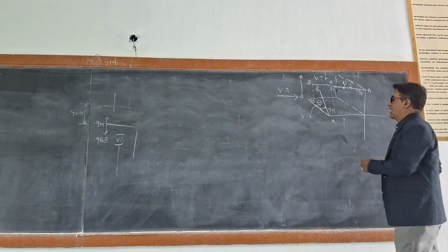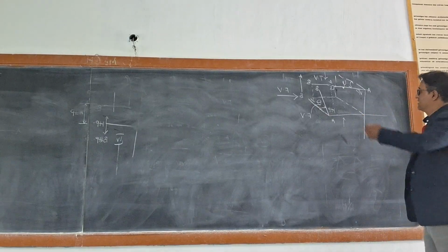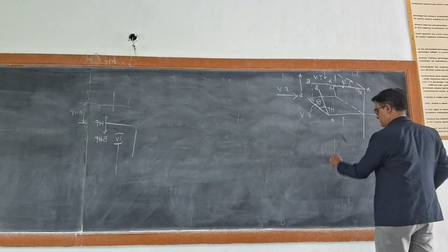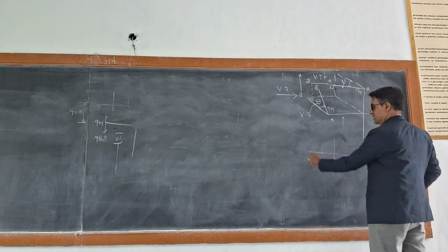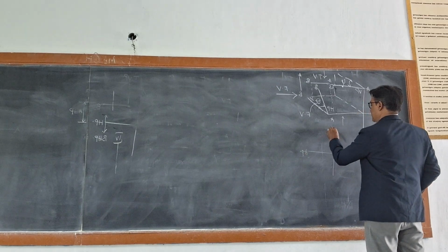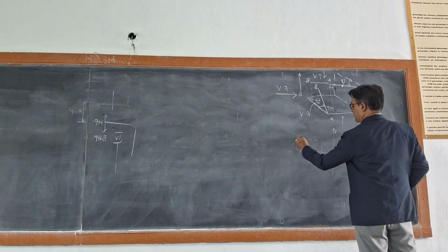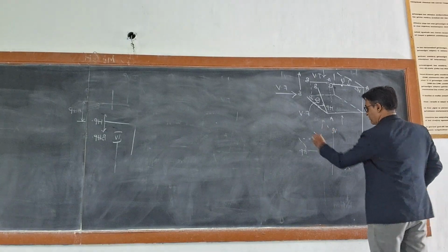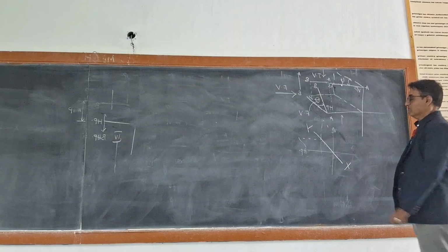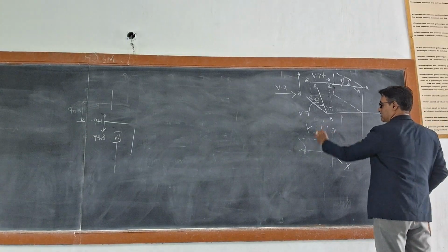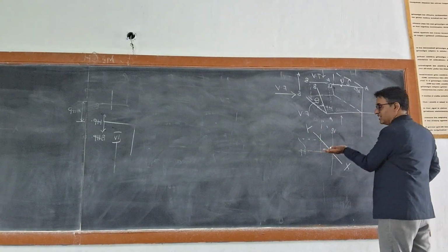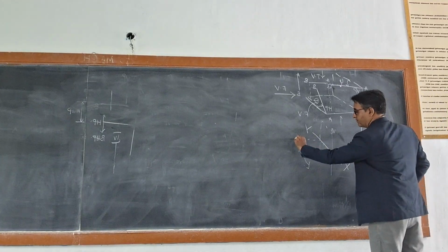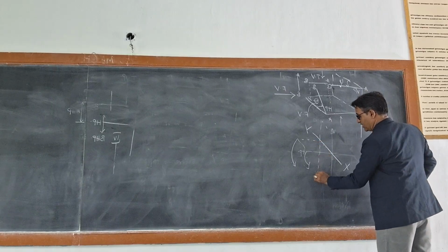Okay. So after discussing all these things, I am going to generate a format. As I have told you, the very first thing is finding the common reference line. Say this is HP, this is VP, right? Now this is your common reference line XY. I can make this plane on an A4 sheet, but this is perpendicular to VP. Therefore, I have to rotate this horizontal plane. Therefore, this horizontal plane comes like this.